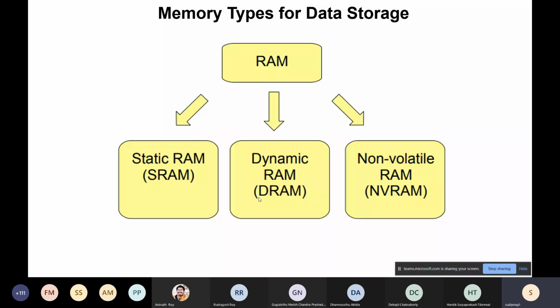But that's not all. DRAM chips are quite fast in the sense that you have fewer connections. That means fewer capacitors in between. In the VLSI lab, we will talk about capacitance in different circuits that we generally don't consider, or you may not have considered so far, as a load. Whenever there are more interconnections, meaning metal connections inside an integrated circuit that are very close to each other, those close metal lines form parasitic capacitance in between.